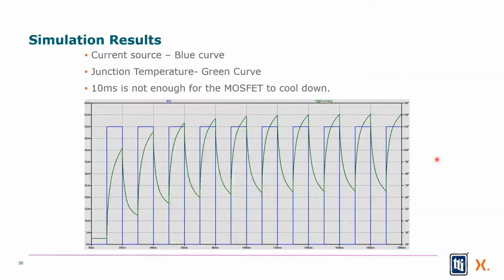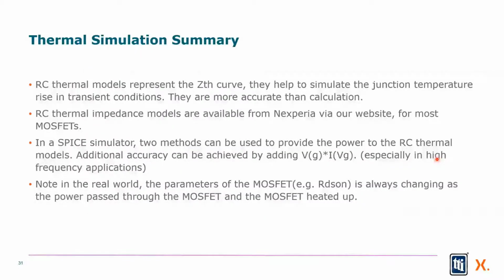And I can change this all I want. That's the nicest part about this tool. So I've done it for just a 50% duty cycle here. Well, what's going to happen if I increase the duty cycle? What if I decrease it? What if the current goes way up for shorter periods of time? I can actually calculate that and play with hundreds of examples before I ever solder a part onto the circuit board.